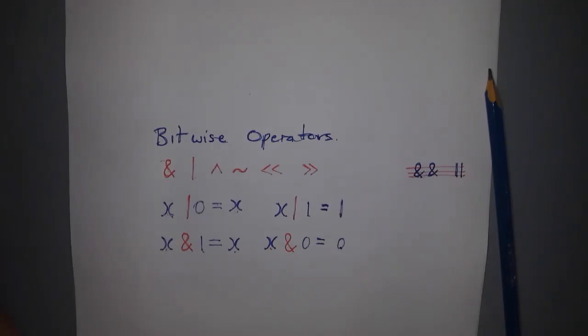Where are we? There we go. Step. There's our internal pull-up resistors getting activated. Our initial value of count, and here's show count. We're going to jump down here, step. What it's going to do is turn off those 3 LEDs. Oh, I've jumped straight to this line here, and it's turned on the particular LED I want.